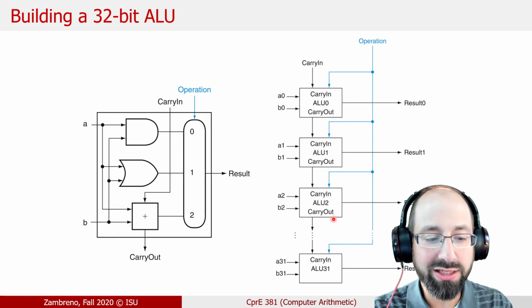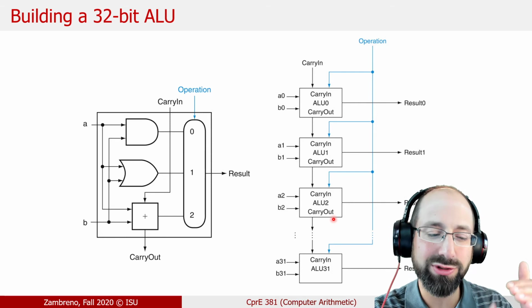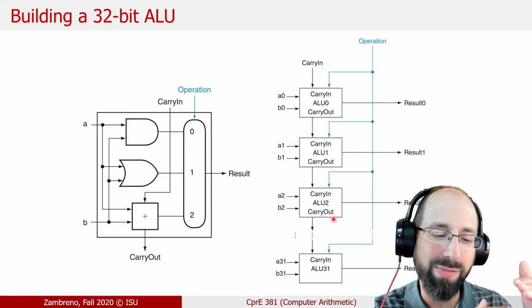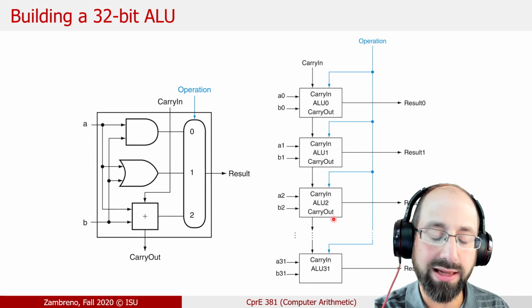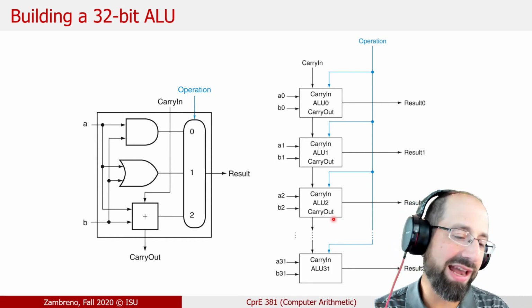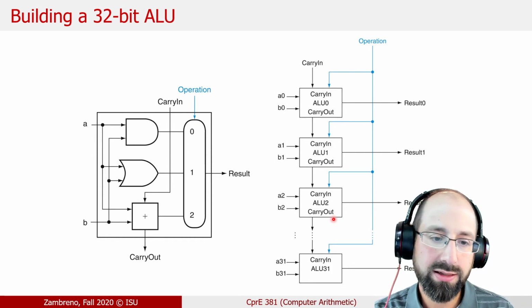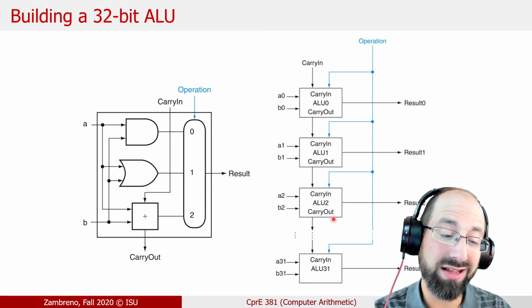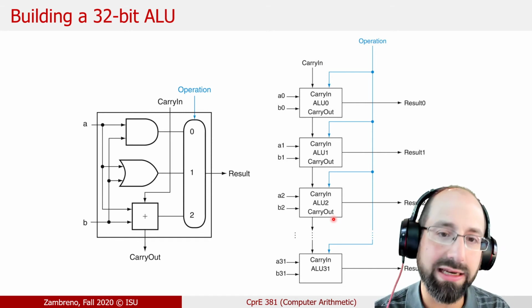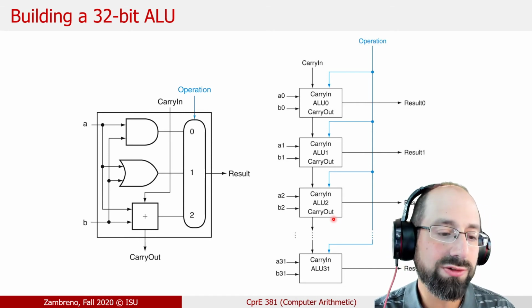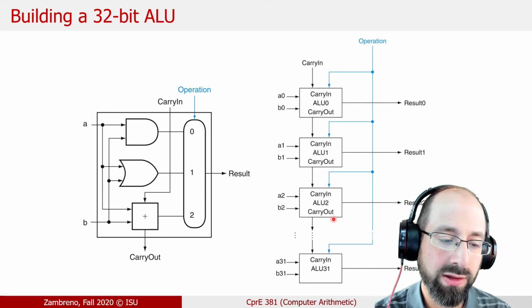Extending the mux potentially. Muxes tend to go at those powers of 2. So this is a 3 to 1 mux, so you already have the right number of bits for your control, your select lines for your mux there, and it would just be adding an additional input to your mux. And that philosophy is why we like the 381 philosophy. It applies to everything that we're using with this mux-based control mechanism, which is let's add an additional instruction to a design that's already working.